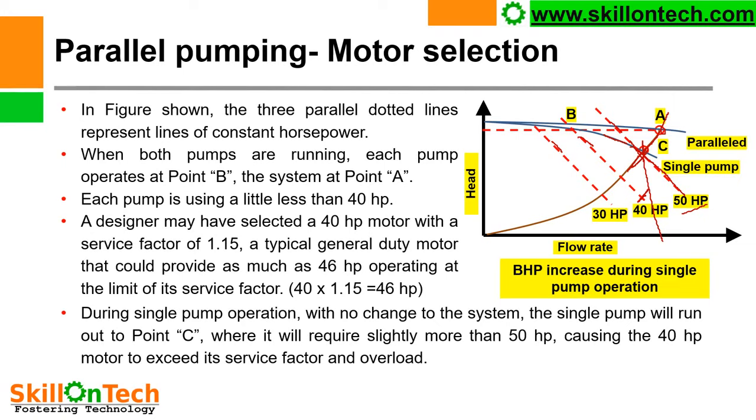So therefore, while selecting a motor for parallel pumping, we must select a motor of a suitable rating and horsepower to meet the requirement of single pump operation.